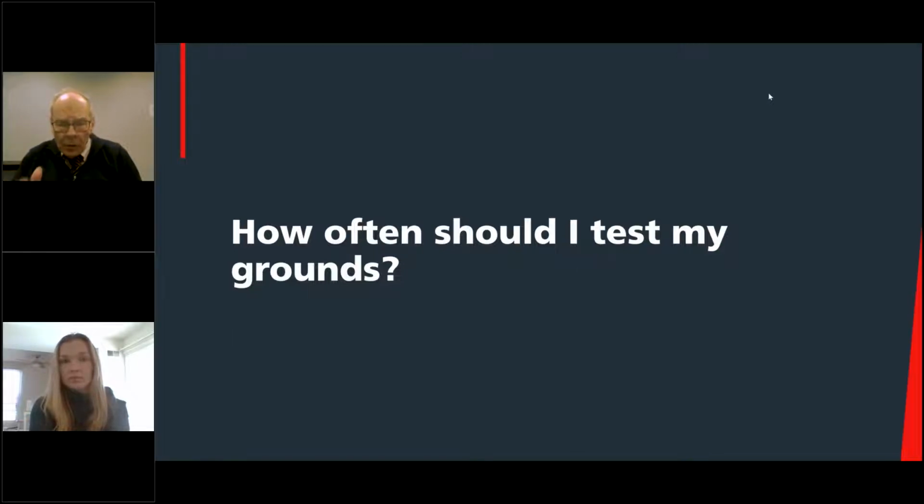But what you want to avoid in ground testing is falling into the same time every year. Select a number of months, like 7 months or 9 months or something like that, because that way you're going to fall around the calendar from one testing period to another.